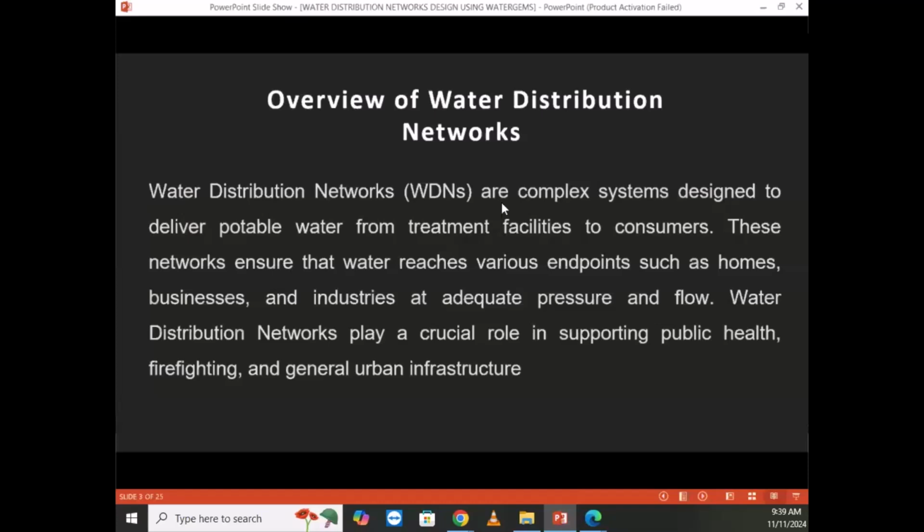Those are secondary tanks. So you will see in our design, you may also design a network so that you will have primary network, secondary network, and tertiary networks. Most of the time, the transmission line is ending at the primary network and starts distributing. But others are taking it to secondary, then to tertiary, and you start distributing water on tertiary networks.